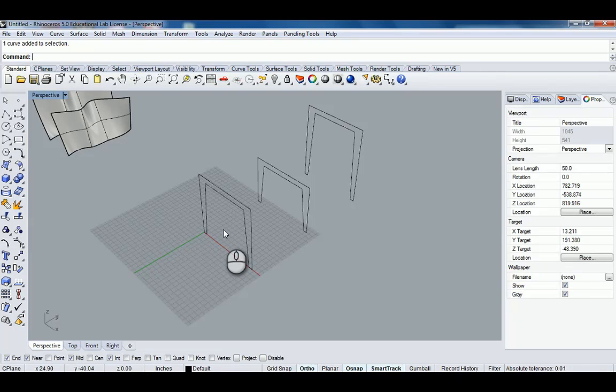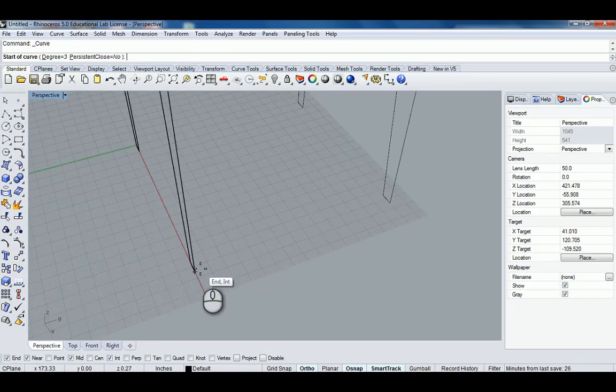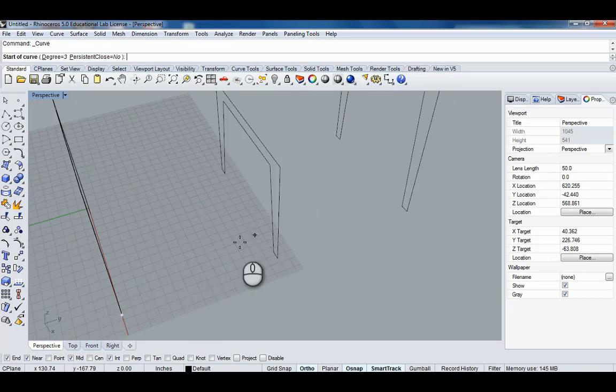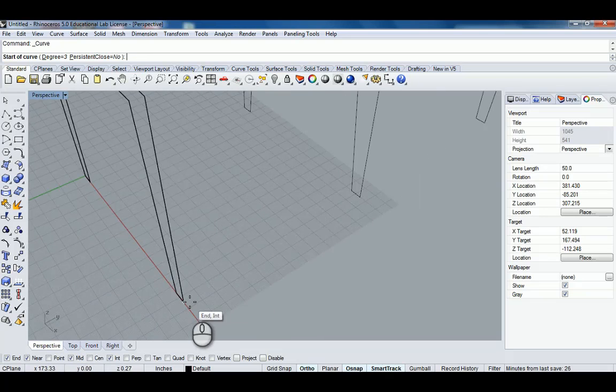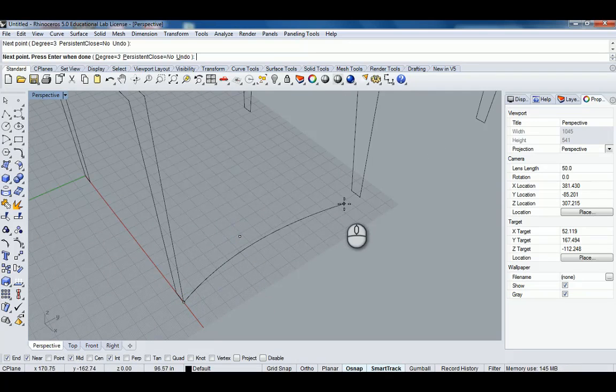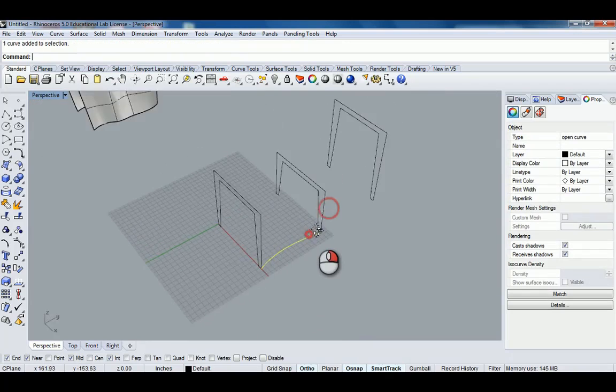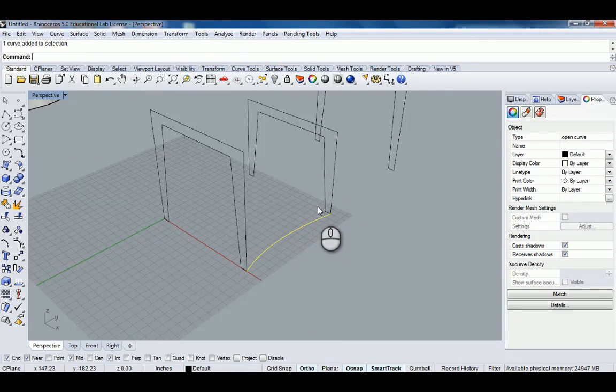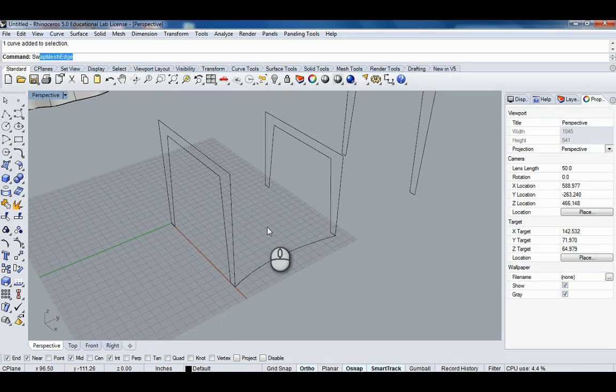So let's, for example, say that we want to extrude between these shapes, but we want there to be additional curvature to the work in the middle. We want a cross-section that changes across the extrusion from one shape to the next one. So let's say that I create a line that is kind of inverted here, almost like a tent structure that's shrink wrapped to the frame. So if I were to type sweep 1 to start, what this is going to do, select the rail.